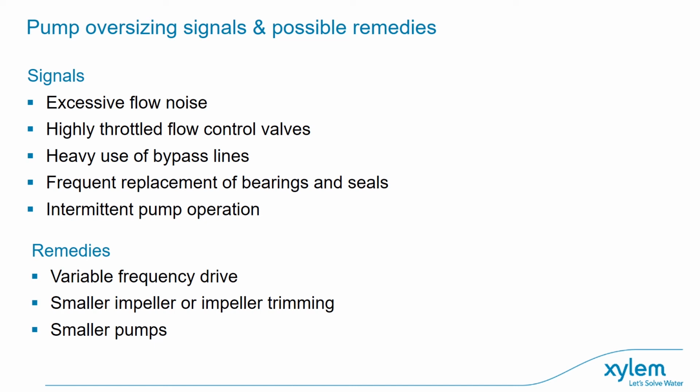You energize and de-energize a system continuously, actually making the system face the axial thrust and all the inertias due to the starting or stopping of a system, and at the same time making it withstand the axial and radial thrusts of the hydraulics, and also all the bends of the piping, for example. Not even mentioning the effort on the motor.